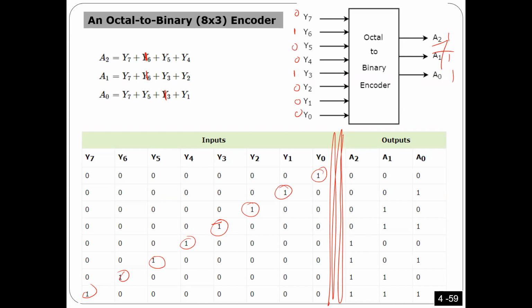However, users may not follow that. If 2 inputs are 1s, based on the design I did here, I got a random number: not 6, not 3, but 7. So I'm going to redesign it so that if a case like this happens, the output will be the one corresponding to the input with the higher number.